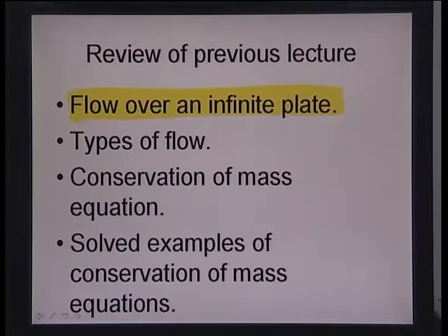a difference between the fully developed region of the flow and the layer adjacent to the plate which has a shear deformation. We talked about different types of flows regarding 1 to 3 dimensional flows and tried to calculate the velocity fields. We also discussed a control volume dx, dy, dz and tried to derive the conservation of mass equation, which is also the first Navier-Stokes equation.